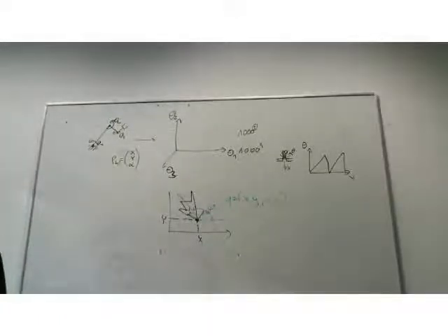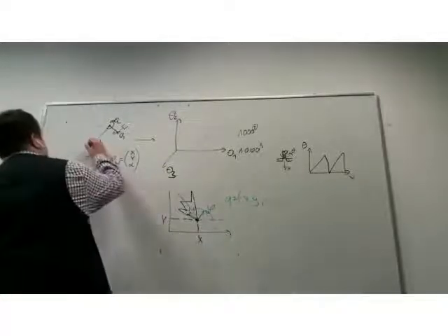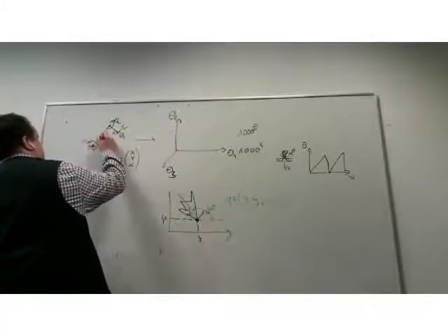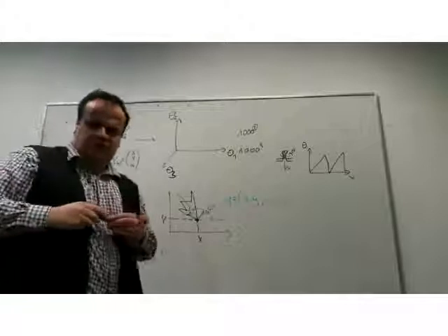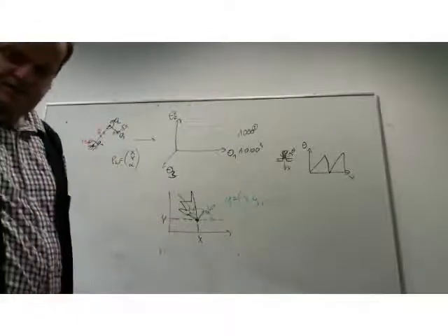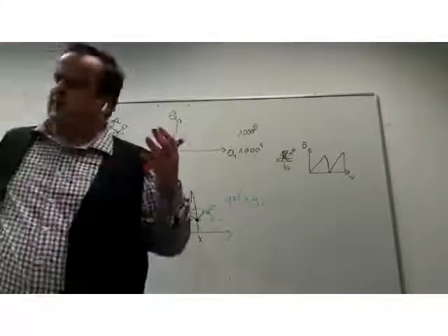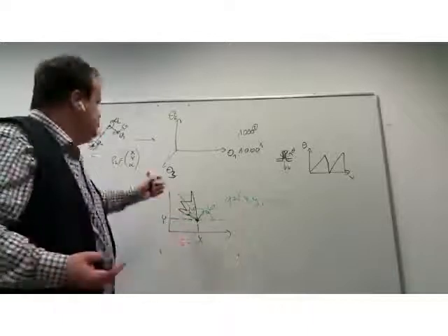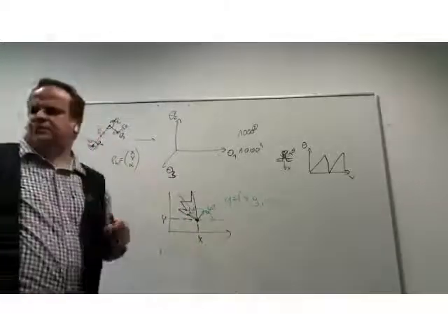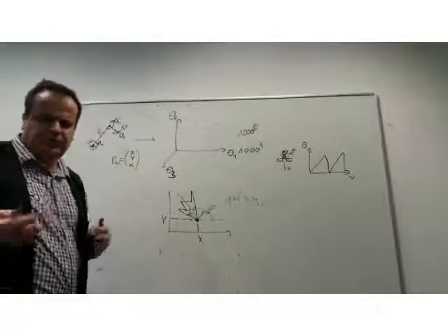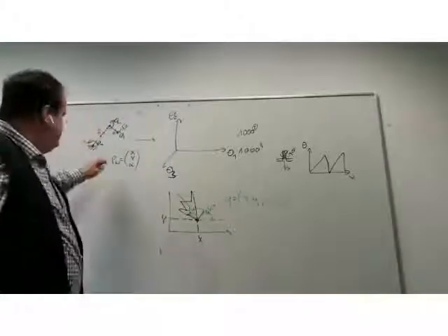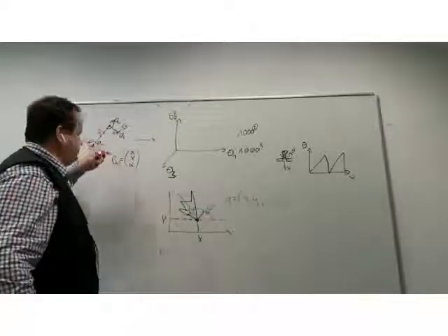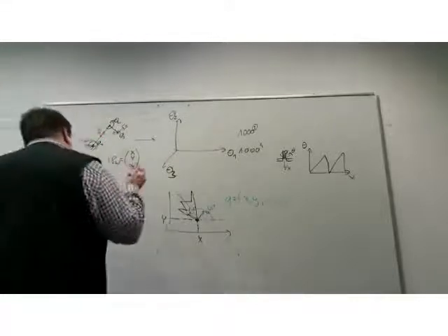And now we know that if we have a robot like this, with some base coordinate frame 0, and we define some new coordinate frame 1, and so on, to define where our end effector ends up being, then without any other constraint, we are free to choose where we place the origin of the coordinate frame and which way we choose the orientations of the x, y, and z axes. So if we have a free choice to switch between coordinate frames, I will write the coordinate transformation equation.